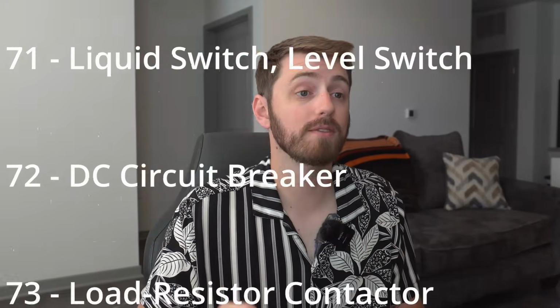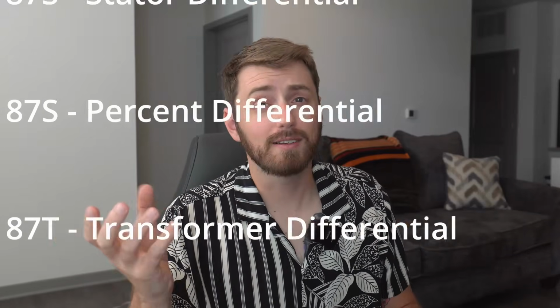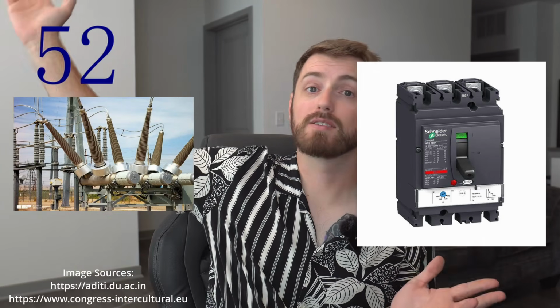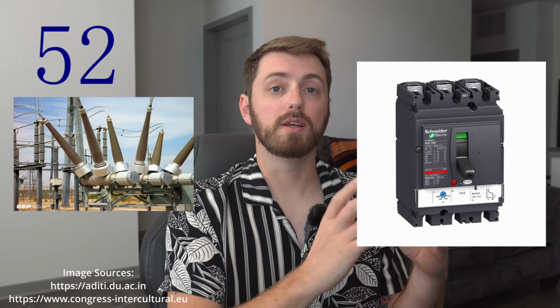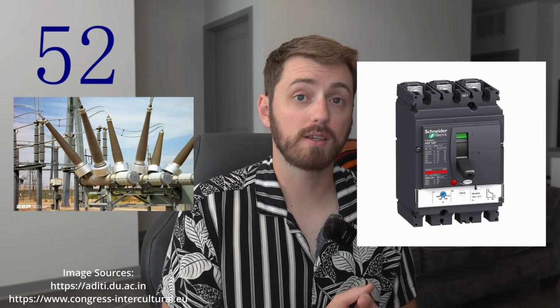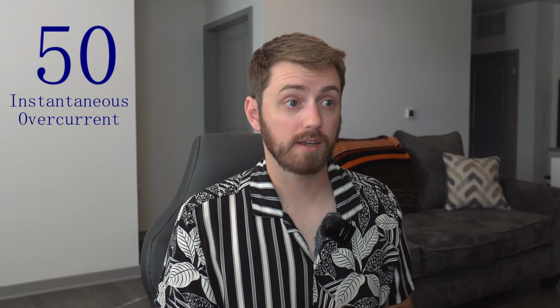You don't need to memorize all of them. I just need you to know a couple very common key ones, and then anything else that comes up along the way, you can look up as you go. ANSI device code 52 is an AC circuit breaker. It could be a big, giant, massive 500 kV SF6 circuit breaker out in a substation somewhere, or it could be a small 480 volt little molded case breaker. Just know that ANSI device code 52 refers to the breaker itself. It's something that opens the circuit, usually has a protection function tied to it. ANSI device code 50 is an instantaneous overcurrent device.